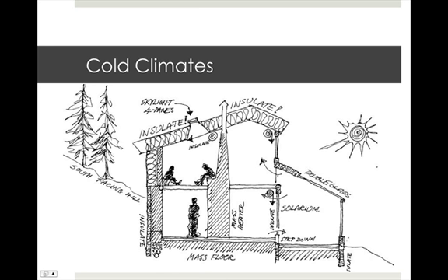In this drawing, the house is positioned on a hill, and you can see this is a south-facing hill. So the main portion of the house faces the south, and then it has this hill and these trees in the back to help insulate it from winds that come down from the north. And then here, this double glass area, these large windows, the solarium, help bring in the sun's heat. This very thick floor helps insulate the bottom near the ground. Oh, and look here, skylights that help bring in more sunlight.